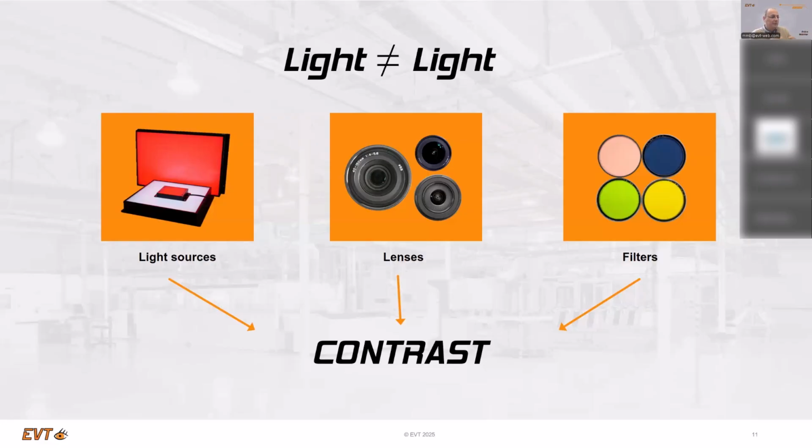For example, if you are in a factory environment where workers have to work or are present, it's very disturbing for them if you use visible light, and if the machine produces very fast and you have to use a flashlight, if you don't use the option of the camera to have a very short shutter time, or for whatever reason you have to use the flashlight, it really disturbs people if there is a flashlight running at 15 to 20 or up to 25 images per second, because the human eye can see it, and you disturb the concentration over time if you use this kind of flashlight.